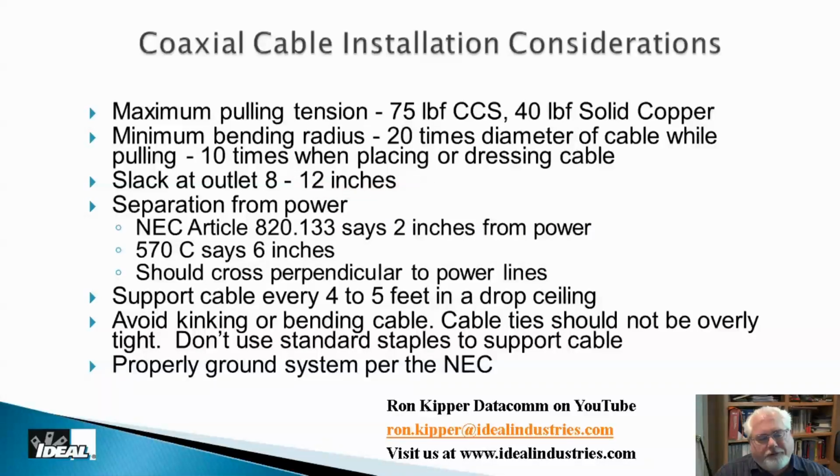Slack at the outlets is suggested to be 8 to 12 inches, and I said a minute ago, make sure you take that 8 to 12 inches and use a backless box, not a box with a back. Code does not require a back box on our low voltage boxes, so don't use them, because people just wad up the cable inside the box.